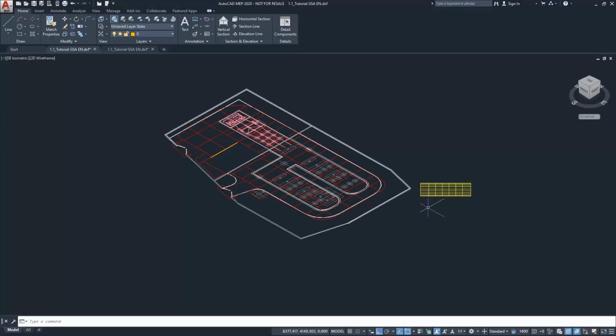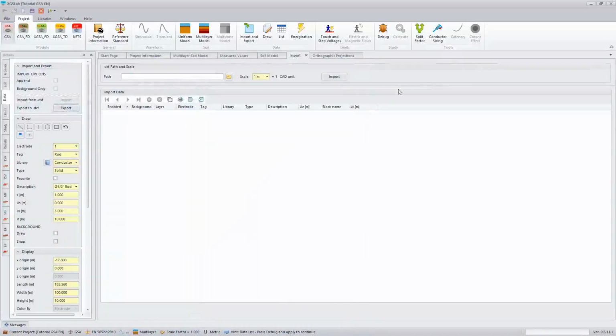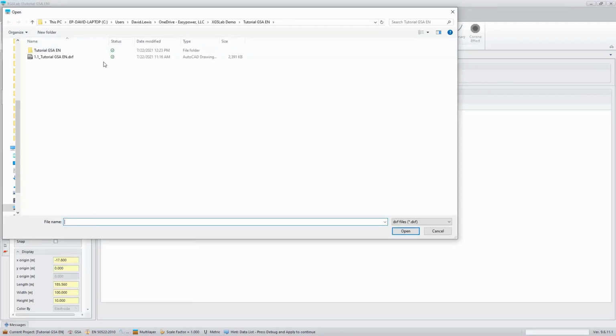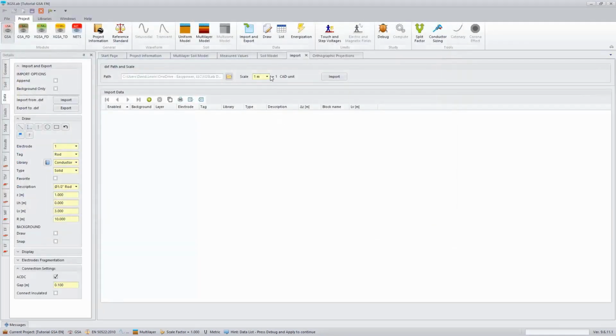You can see on the right, we actually have a three-dimensional tank represented by this yellow conductor. And we won't have to shift this because it's already three-dimensionally drawn in the CAD program. So let's go ahead and import this. First, we have to navigate to the directory where we've actually placed our DXF. Next, you'll want to set your scale that they're using for the CAD program. And then we'll start importing the conductors based off of each layer.